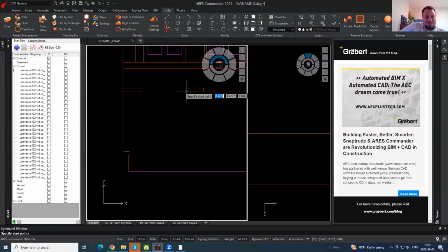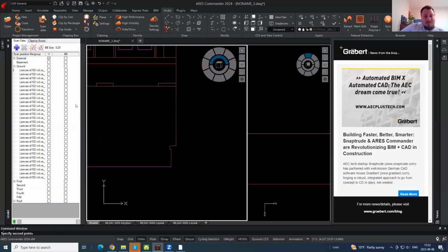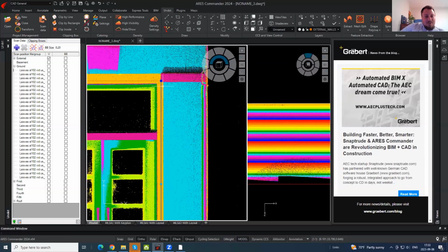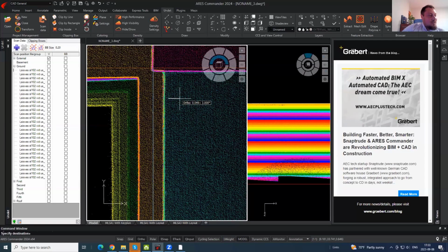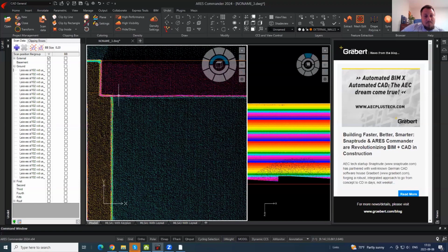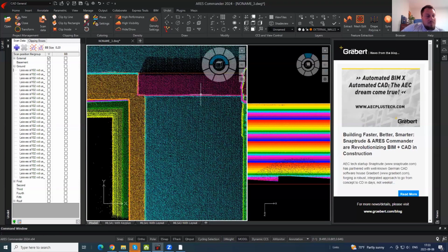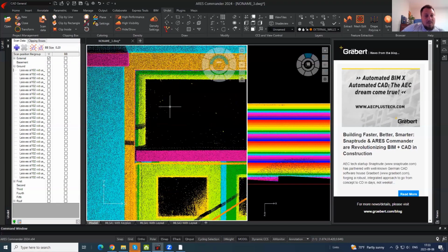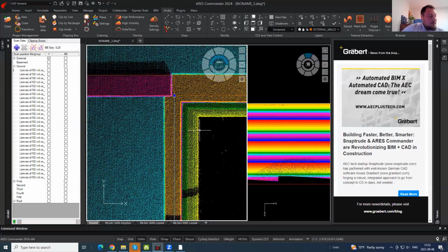And now when working more and more with vectorization modeling, you see that the coloring mode by plane is the best one. And even for our customers, who are asking if we should take laser scanning with true colors, it means spending more time in the field to do the scanning and later take photos with the scanner. It could take twice as much time.